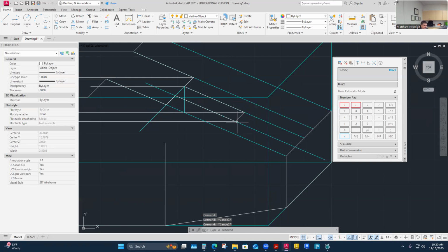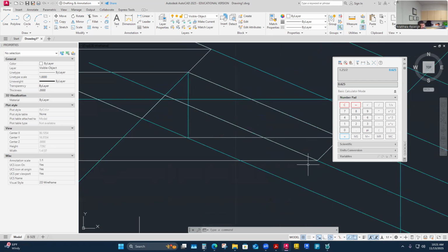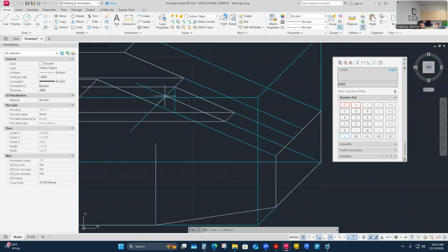And then I came back this way, 1/8 of an inch, and created this intersection point too. So I made another copy of this to that point. So I had this long intersecting construction line here. And then I had to add another construction line here. On that 45-degree projection plane, I extended this line as construction work so that I could create this intersection point here with what comes up from there, where it crosses is where this terminates.